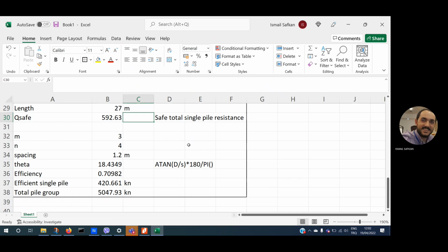What do you pay for when you construct piles? Concrete. How do I calculate the concrete here? By height, right? You know the total quantity, how many piles, you know the diameter, and you know the total depth. So you can calculate the volume of concrete. It's also important for excavation, right? Because you pay per meter of excavation of piles. This is one option, okay?